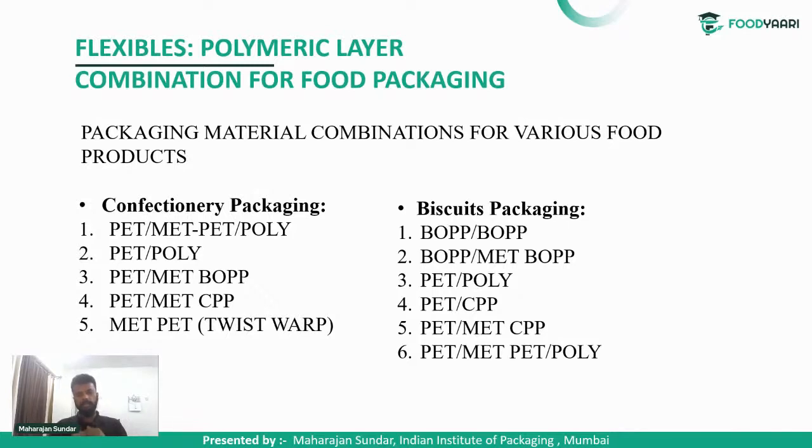In biaxial orientation, it is oriented in the machine direction and the transverse direction. Biaxially oriented polypropylene films give great water resistance compared to normal OPP films, unidirectionally oriented polypropylene films.